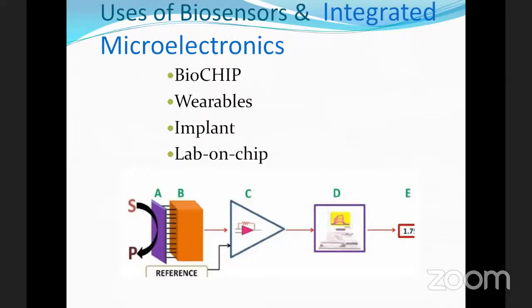The use of biosensors, apart from the applications in various domains, is that biosensors can be used to construct a complete instrumentation setup. A biosensor detects an electrochemical or biological process and converts it into a suitable electrical form. After it is converted into an electrical form, it must be connected with a display that will show values like blood glucose, as point of care devices.